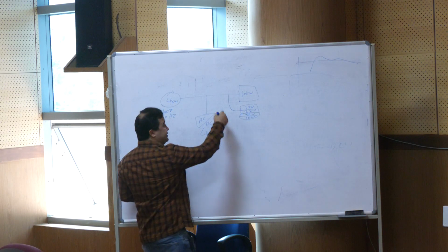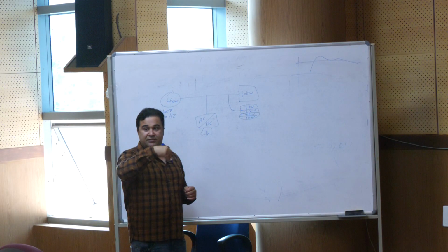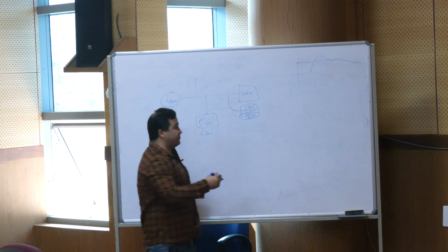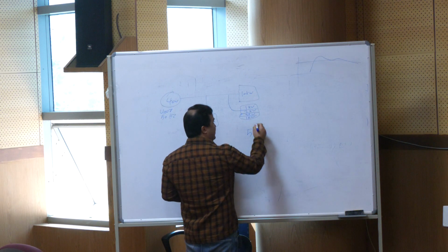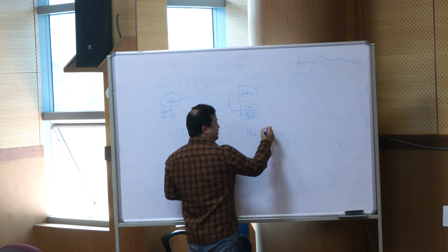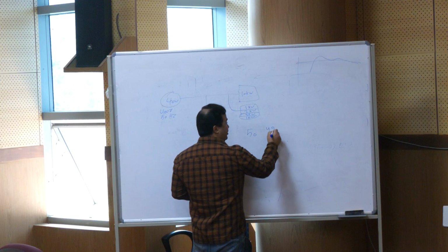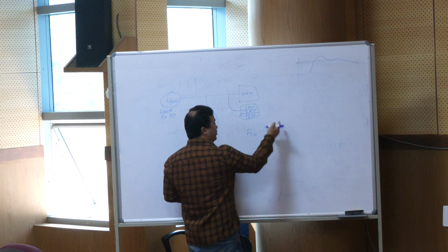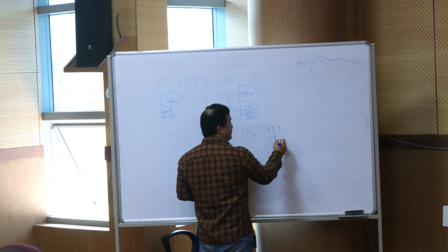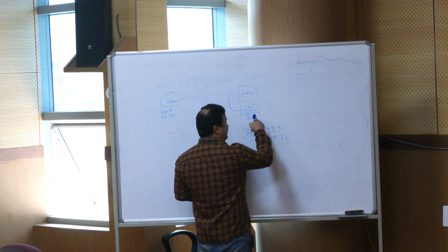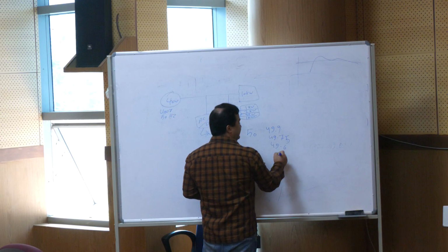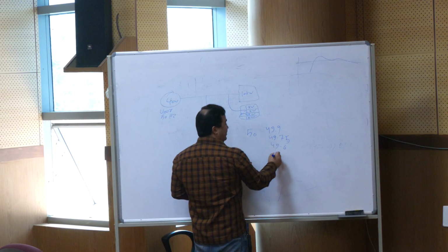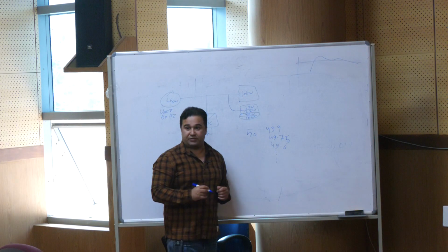When the load increases, the frequency drops. The frequency was 50; when it was 1 kilowatt more, it became 49.9, then with 2 kilowatts, 49.75, and then with 3 kilowatts, 49.60, and you see that the voltage is dropping.